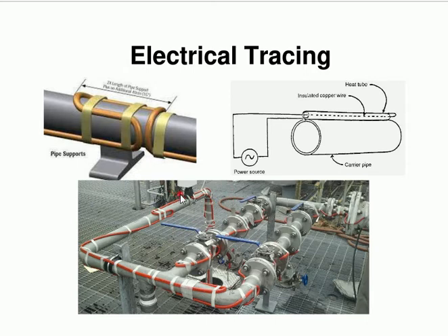Ideally, what you would do is stick some lagging around the pipe as well, which they haven't done here, but if they had, you wouldn't be able to see anything. So you would put some lagging around it to make sure that the heat is contained, that you're not heating the factory oil, but that you're heating the pipe. So that's the important thing. This looks to be outside anyway, but that's one way to do this. Interesting as well, when you look at this one here, they put a lot of emphasis around these bends, put some loops on there to put the tracer on.